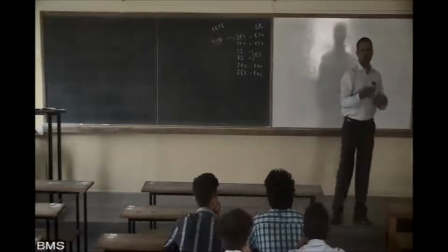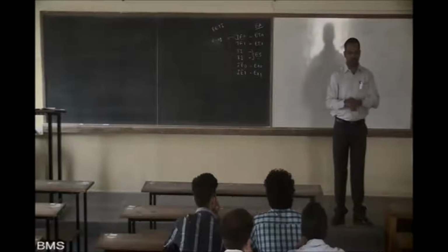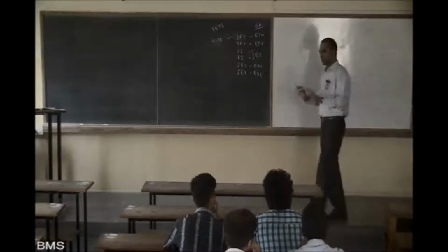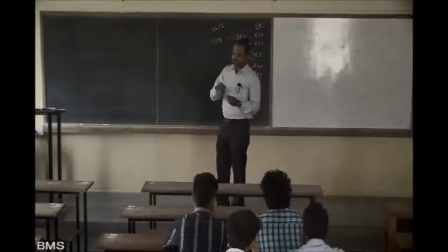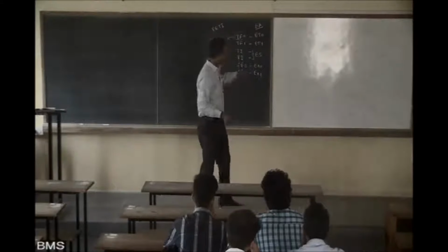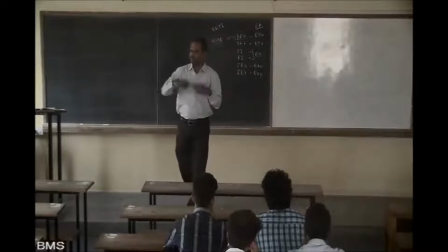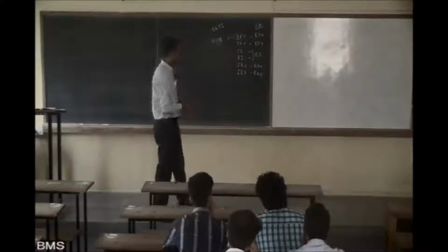You don't need to do that polling now. Is it clear? This is a very, very fundamental phenomenon. They are there, but it is not enabled. We have enabled it, meaning that whenever TF0 is set, PC will change its value by itself. Is it clear? Done.